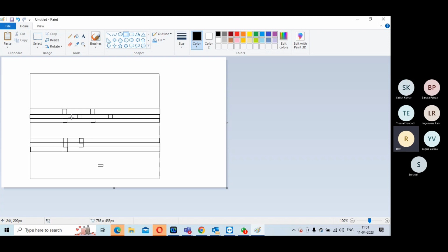Basically, you can have a tapless library and a tap library. Earlier we had with tap and without tap. In a tap library, every cell will have a tap, meaning there will be a notch which connects to the substrate. Then you don't need a tap cell in your design at all. But the problem is every standard cell has to accommodate that, so the standard cell becomes bigger, its area is high, and overall consumption becomes problematic. So mostly all designs today are tapless because they found the tap library is a waste. Every standard cell has it, so what is the point?